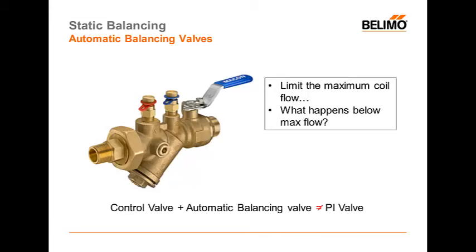One very important point about automatic balancing valves: if you take an automatic balancing valve and pipe it next to a standard pressure dependent control valve, it's not the same behavior as a pressure independent valve. That is a common misunderstanding in the industry.